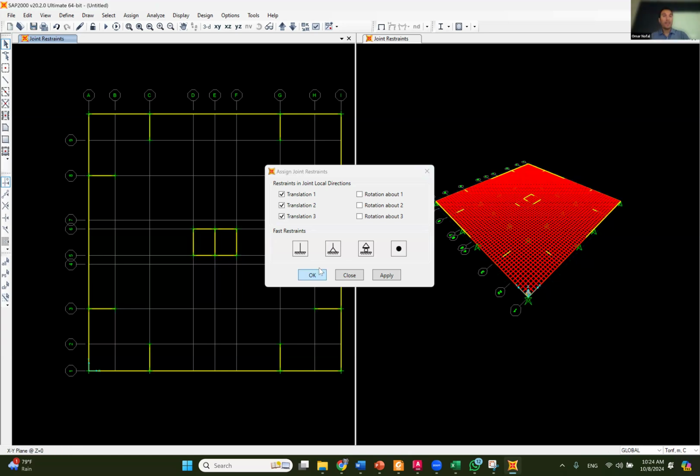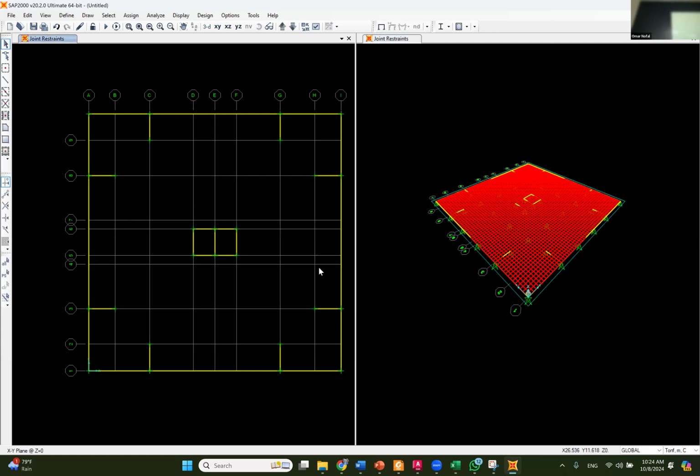All right, so what I did right now, I put hinges at the start and at the end, but it should be hinges all the way at this location. Why? Because there's a wall at all these locations. The thing is, I can do this section and adjust its stiffness, because right now I'm not looking for reactions on the shear wall. I'm looking at designing this slab system in a good way. I want to model this slab system, find the reinforcement and design just the slab, not the columns, not the shear walls. So to do this, I need this slab to feel that there's a shear wall here.